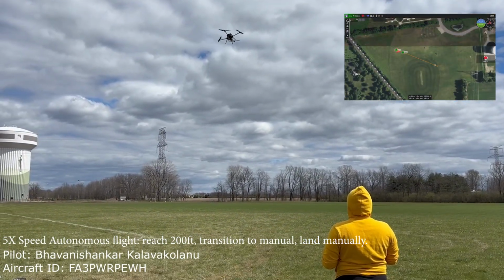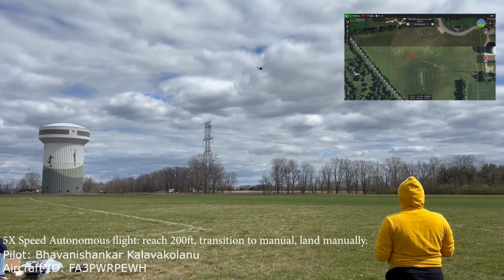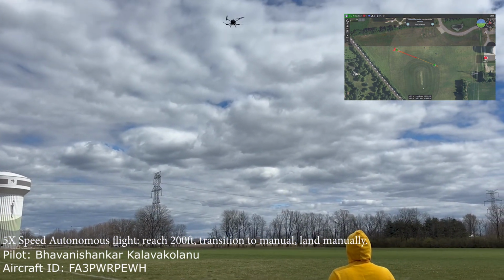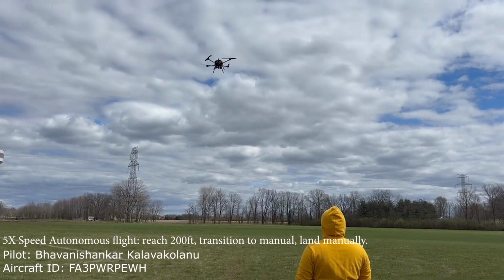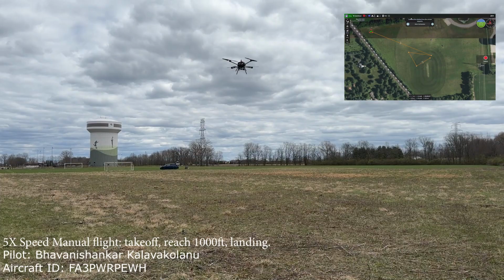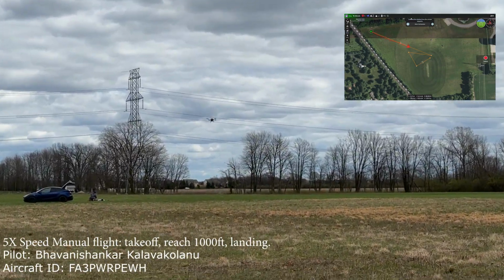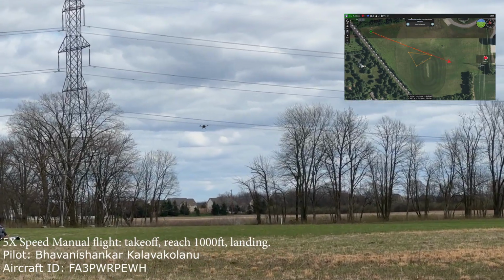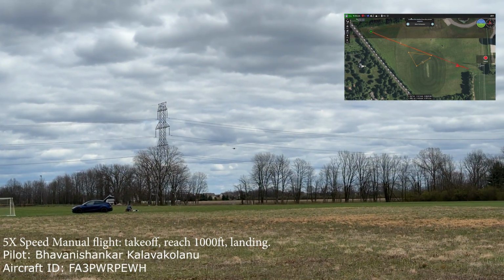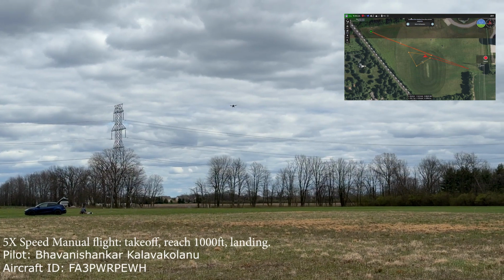Throughout our second year in the SUAS competition, the team has learned and grown in many different aspects. This year, the team successfully designed, manufactured, and tested a quadcopter drone that can meet all specified competition requirements. For image detection, the team developed an object detection and localization system for the UAV, dividing the task into shape, color, and character detection. Using YOLO V8 for both models, they achieved a high accuracy through domain randomization for diverse dataset creation. The system, running on a Jetson or an AGX, accurately localized targets in 2D space using a sophisticated algorithm while employing the CZR-10 camera system for clear imaging and stabilization, meeting competition requirements.